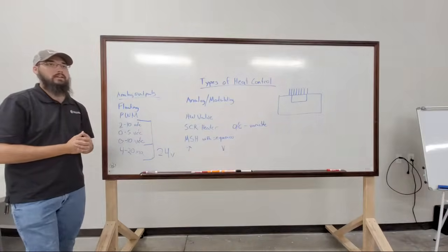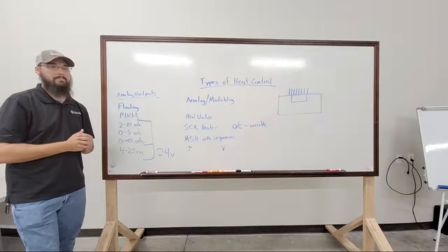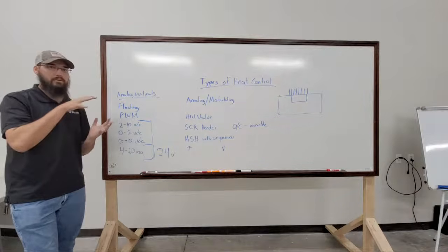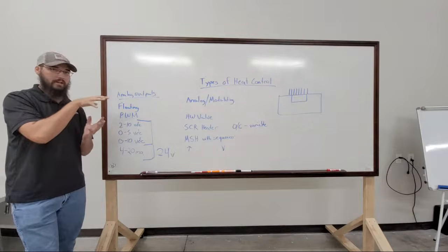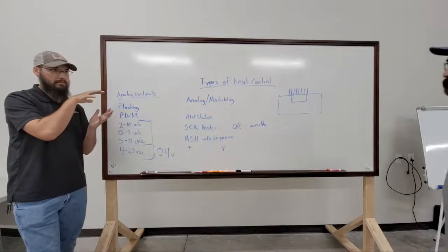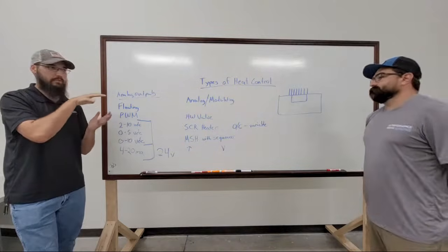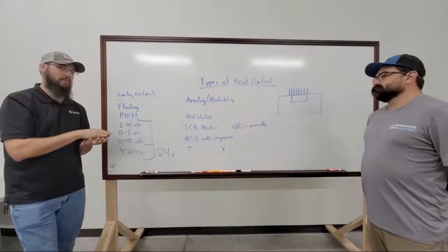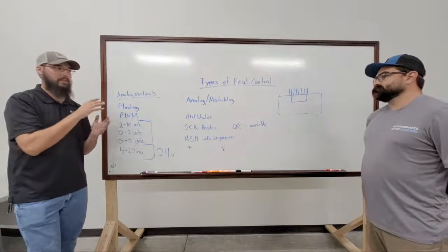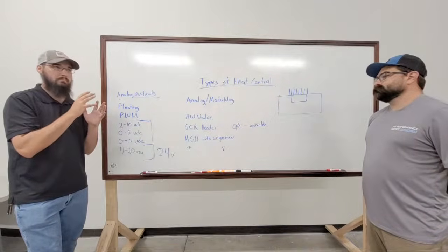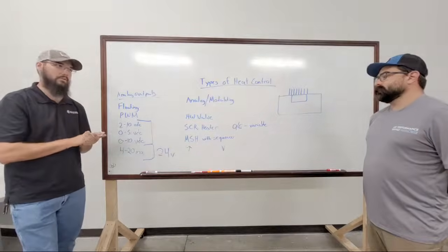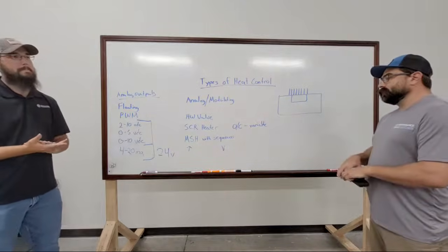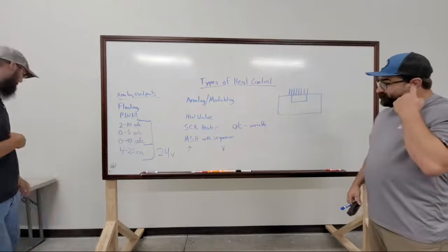If they do dry fall, yeah, ceilings paint and open architecture. So it's very critical. Anytime you have any type of retrofit or anything in the building, you protect that heat sink, so that that's gonna make or break that SCR's ability to survive. Yeah, they're not fun when they blow up either. No.